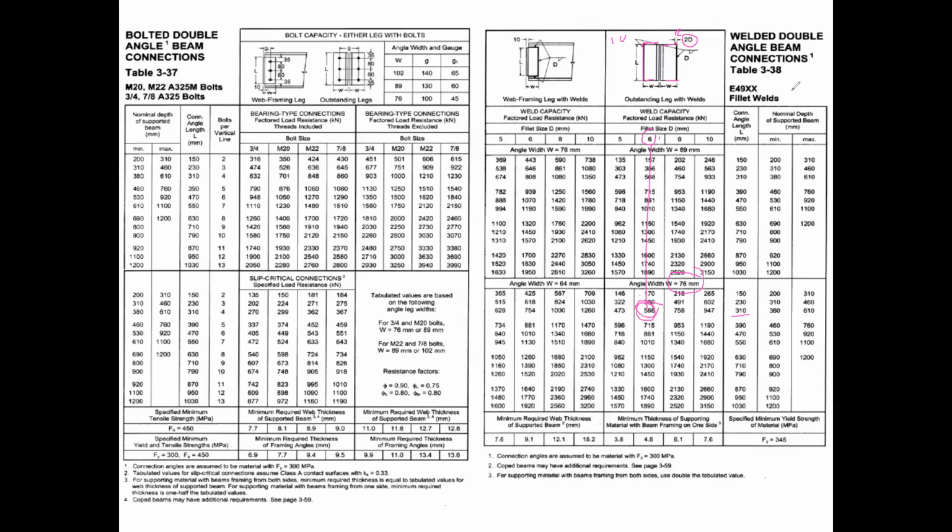So that's where I find the value of the weld size, based on, like here we had 310. Once we took this geometry, I take that geometry and bring it to this side. Once I decide that this is going to be the size of the angle, I use this part of the table, because if I was going to use an 89, I would use the upper one. I go look for a VR value that's greater than my VF. I hit one right here and I go up and see that a 6 millimeter weld will be sufficient to give me at least 535 millimeters of resistance.